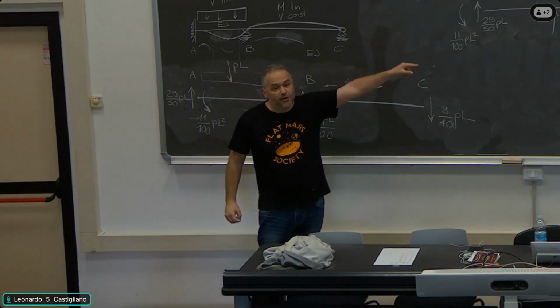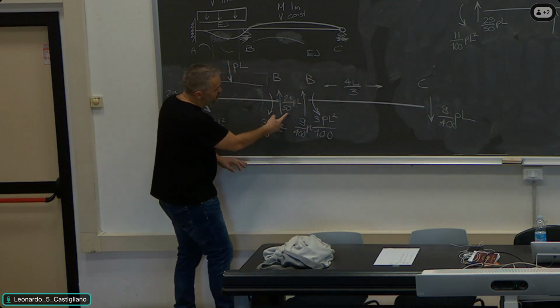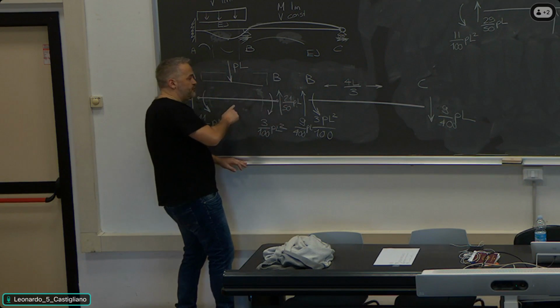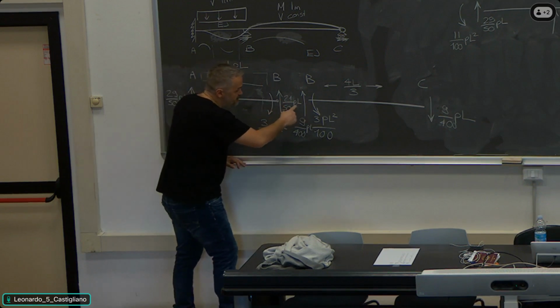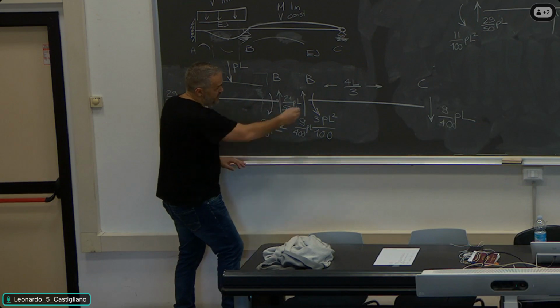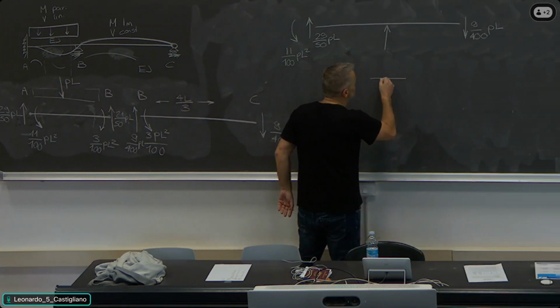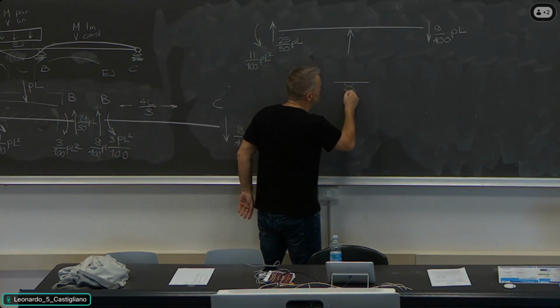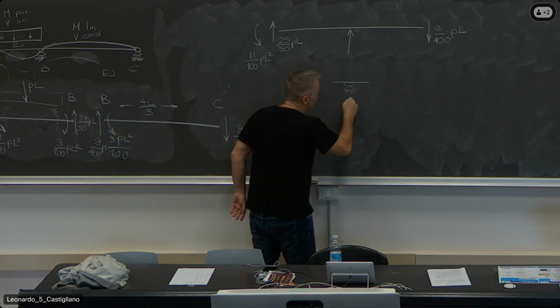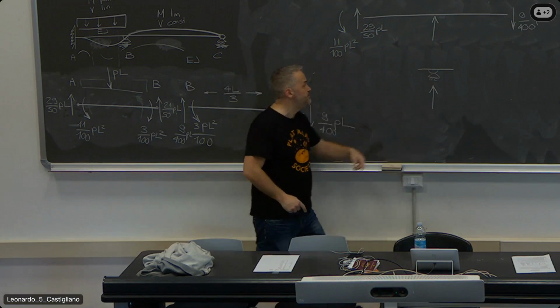You may have problems with the center support. Look here what happens. At the center support you have this shear force on the first span, this shear force on the right span. Okay? They are both upwards. You have to imagine that at the center support the situation is like this. You have the roller, you have the reaction force, which I marked here upwards.